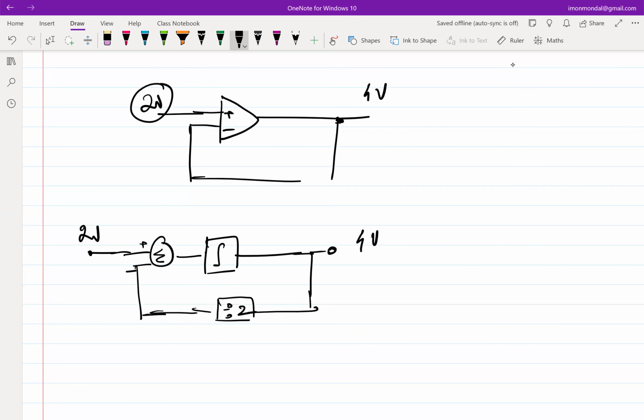So just like this, in case of a crystal oscillator, it is very difficult to get very good crystals operating at gigahertz frequencies. Crystals are piezoelectric type of devices, so they do not operate at multi-gig frequencies. They typically operate at megahertz. More expensive ones operate at probably 100 megahertz or so, but typically the stuff in your cell phone will operate at tens of megahertz or so. But you still need something of the order of gigahertz, a few gigahertz, right?